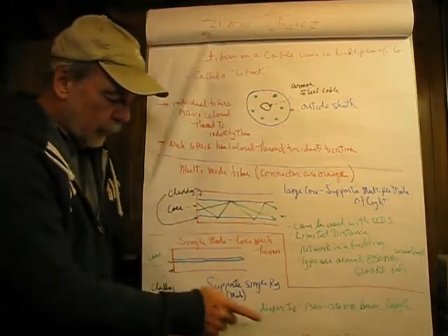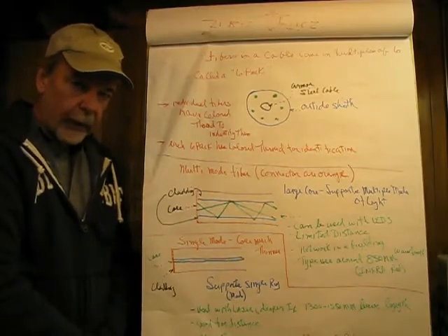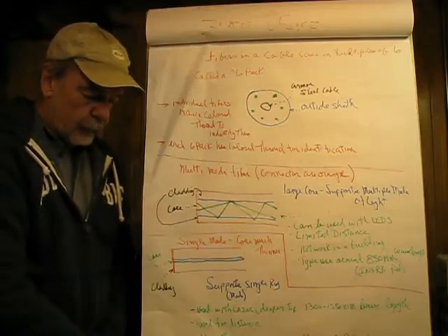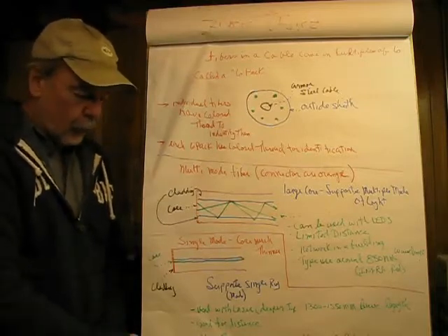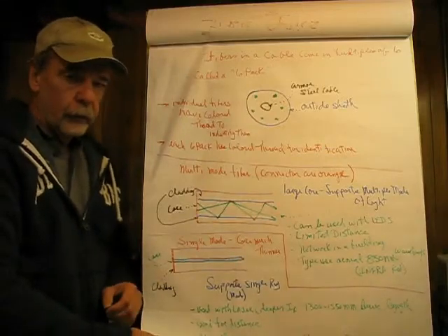And single mode jumper cables are not orange, they're either yellow or black. So it has to be very clear what the jumper's for, because if you get the wrong one in the right place, what's going to happen is a loss. And there's absolutely no question about that.